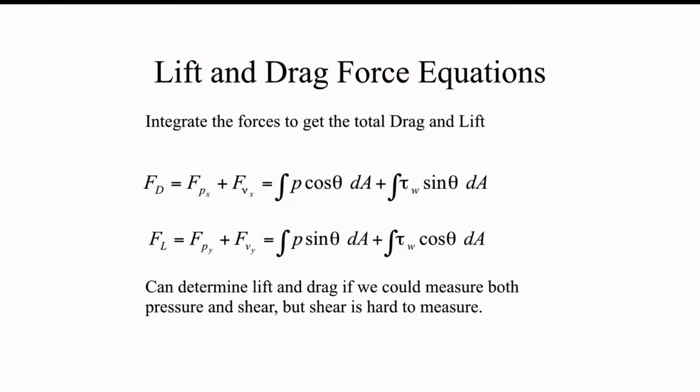If we want to know the total lift and drag force, we need to integrate all of those little elemental forces to get the final results for drag and lift. If we can measure both the pressure and the shear forces, these ones and these ones, then we could just do this integration over the surface and be done with it. However, we've got a problem because shear is really hard to measure on a surface. So that's where we're going to need to do some fancy footwork.